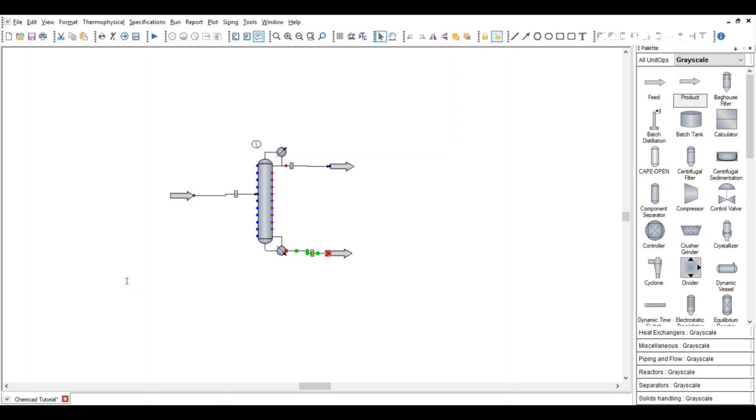Another of the components that we need is hexane, which I'm typing now on the bottom search bar. And I can click on it and click this arrow to add it, or I can double click and it adds it as well. For the last one, find pentane. Now, you could scroll down this bar to find it, or you can type it in this search box here. Be sure to select the correct pentane. We've got isopentane and pentane. We want just pentane. Then select OK.